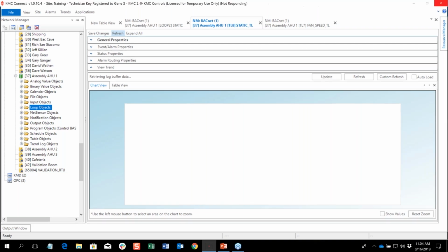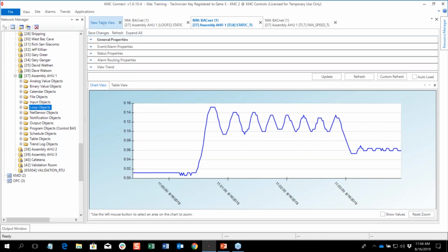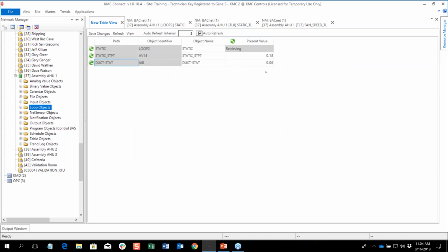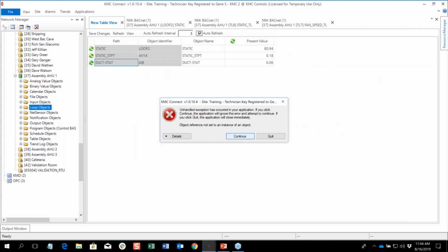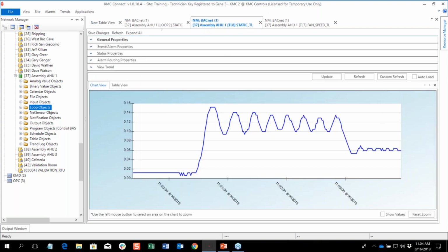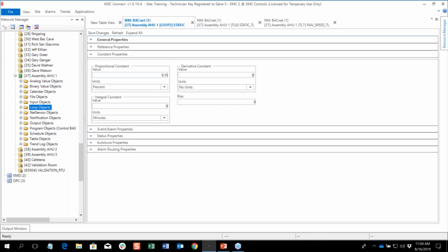Sometimes very basic things, maybe a cabinet heater or an induction unit, that might be an open loop kind of control where I just know that again, if my outside air is 30 degrees, I know that I need to have 50% of that valve output on to get a response. Generally, everything we do, whether it's inside of a loop or reading and controlling a temperature, is going to be a closed loop for most automation functions.